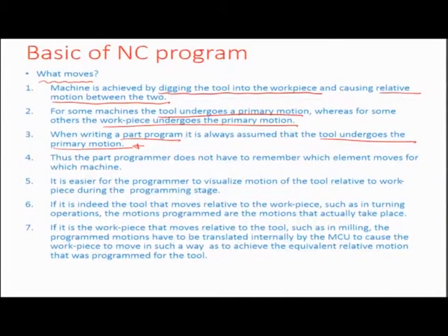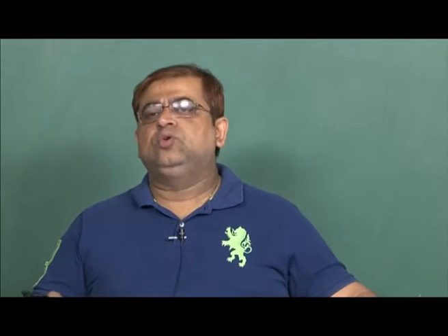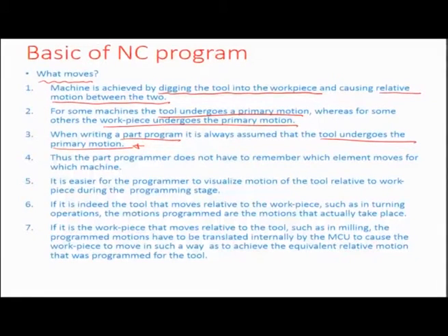That is how the controller has been set up and built, and there are some algorithms which give you an option of deciding whether it is the tool or the workpiece which would move. But that is of no significance or concern to the programmer, who always assumes that he is a part of the tool and moves along with the tool. So, this is a very important aspect.